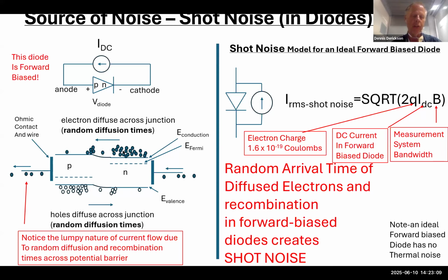There are so many electrons, nobody's interfering with them. But when they start diffusing to the left-hand side in the P material, these electrons encounter a region that is hole-rich, with many holes. And so when these electrons encounter the many holes, they're going to recombine. That electron and that hole will combine and annihilate each other.